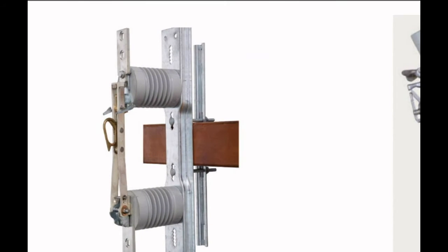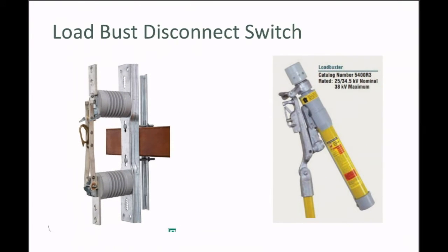You unlock it when you grab it with the hook stick. You'll see these used as inline switches, mid-span. You'll see them mounted to poles. Fuse holders operate on a very, very similar set of principles, although they don't have a locking mechanism. And if you take a look at this, there's no presence of a secondary contact. So on its own, this switch is not rated to break load.